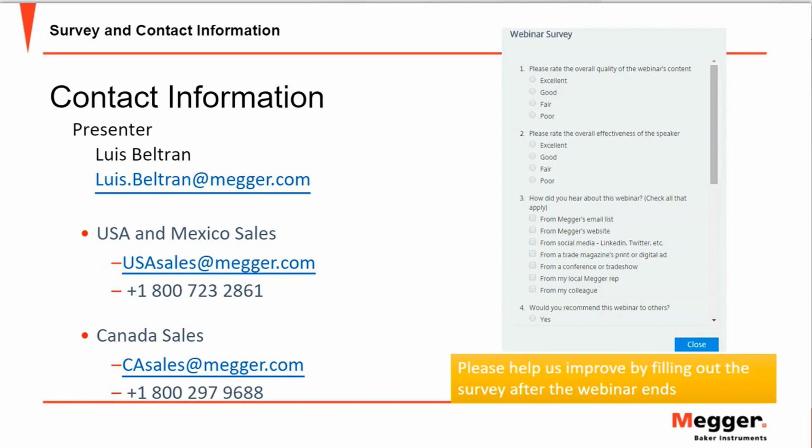For example, if we have motors in the industry, in the field, that have a pulse-to-pulse error of around 3%, it doesn't make sense to set the PP error to 10% because most of the models have only 3%. So we can set the alarm or threshold at 5%. In that way, we are setting the limits for the thresholds.